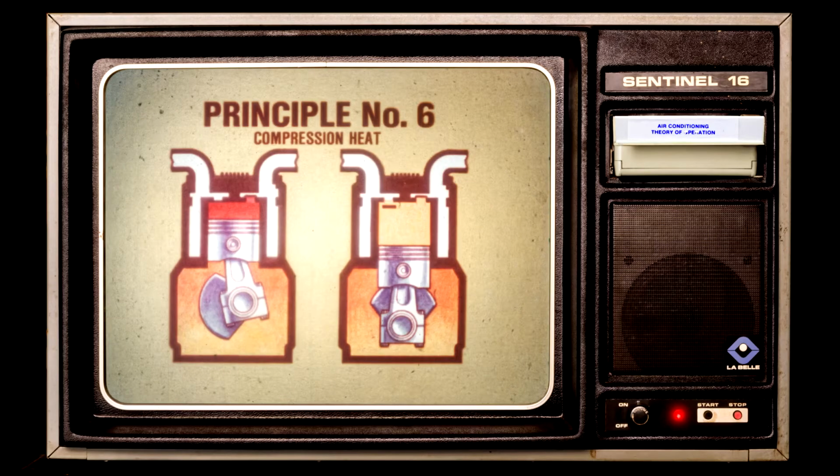Here's principle number 6. Heat of compression. As a vapor is compressed, the temperature and the pressure of the vapor increase, although no heat has actually been added. This is the principle used for diesel engine ignition.